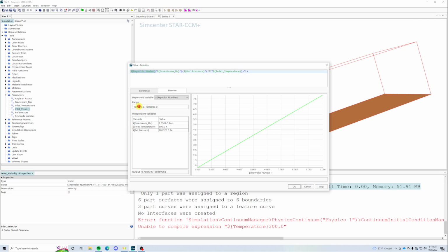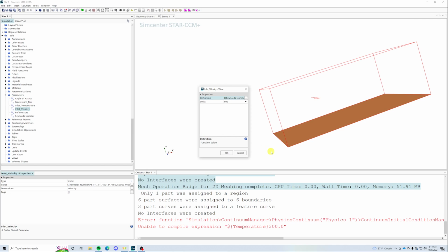I believe that. We could also tag an extra 0 onto a couple of these. So if we wanted to get to a Reynolds number of 100 million, we'd need about twice the speed of sound. 10 million would be 75 meters per second, about 20% of the speed of sound. Makes sense, more or less. It's a relatively big wing. 2 meters chord is actually pretty large.